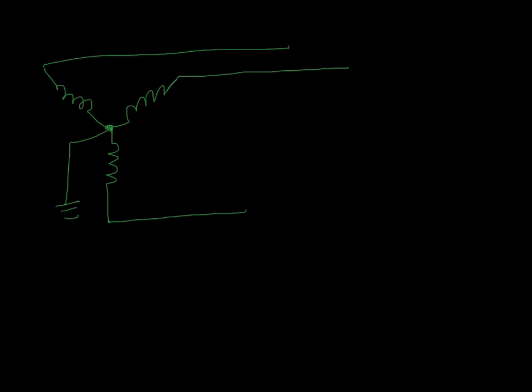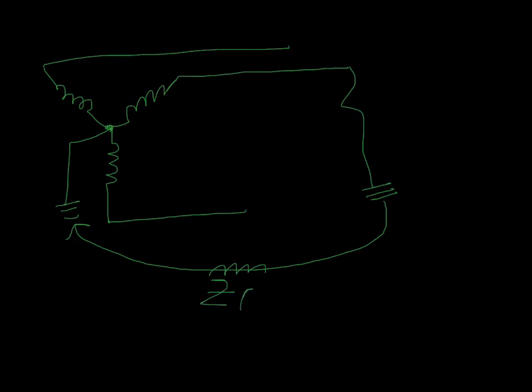It is ungrounded. You have phase A, B, and C, and here you have the neutral coming out, and it's grounded right there. Now, suppose you had a ground fault happen on, say, phase B. What would that look like? So you would have this go to ground right here, and then you would have the ground current run through here and back up through this transformer here. Now, the resistance in this ground, the path that the current takes, the resistance that it faces, let's call it Z ground.